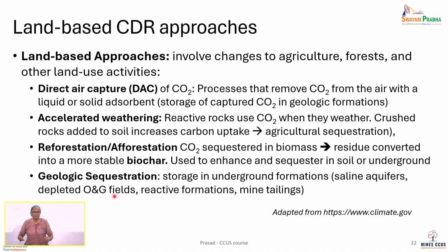over 10, 20 acres, thickness of 10 feet, maybe 20 feet, 100 feet is even better, and a porosity of 20%. We can do the math to say, and we'll do that in class next week. We will calculate how much capacity you get if you have a pressure differential of 500 psi to work with. Usually we don't have the luxury. Usually we have only a few hundred psi that we're working with.